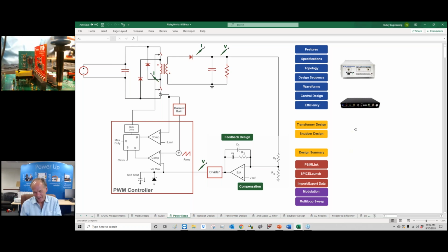Do you gain anything? Well, often a flyback has to have safety isolation in it. As you shrink down, it doesn't keep shrinking. Core losses start to climb, and other things start to climb up. Most of the world is stuck below 130 kilohertz because they can't go into the higher EMI band. But half the world has realized we can switch higher. The filter components are smaller anyway, and we just do the design better so we don't generate so much noise.